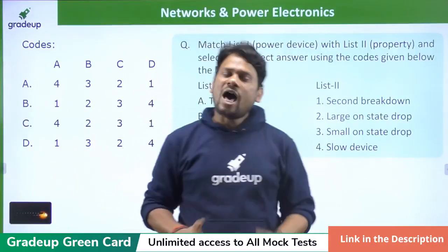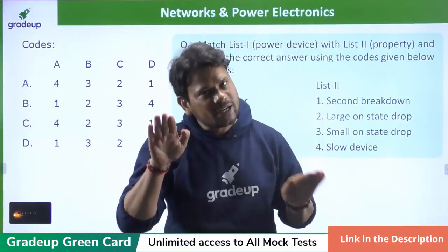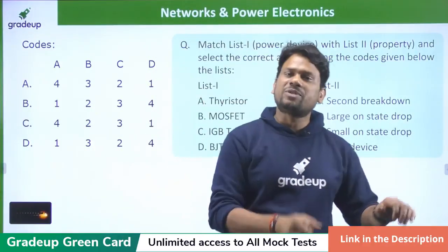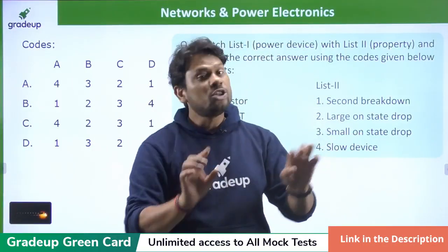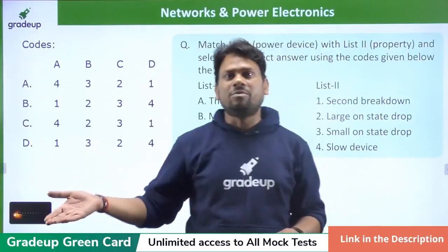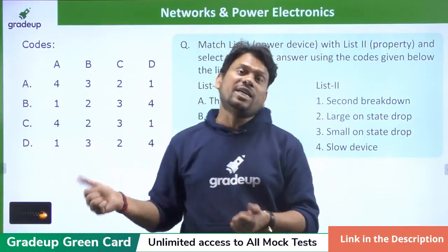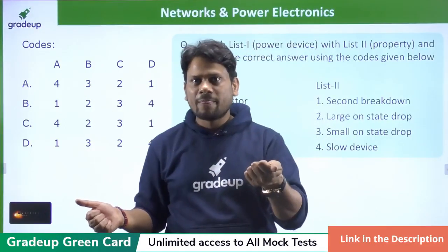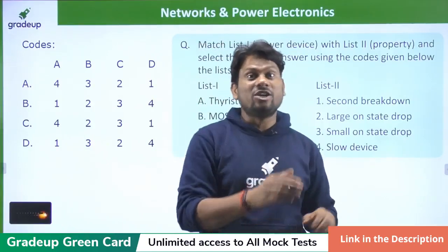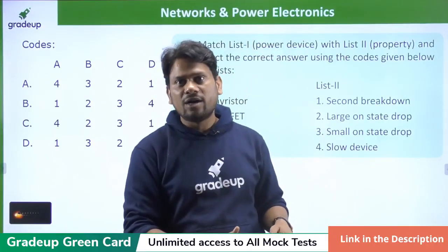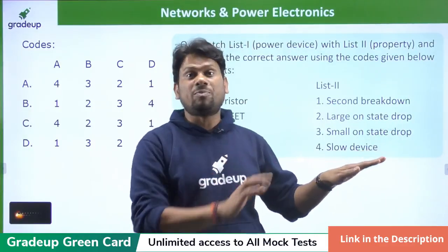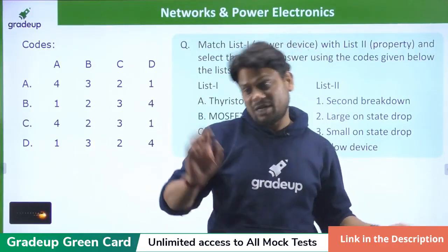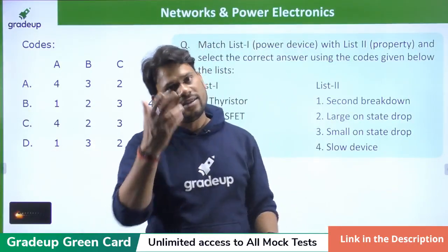आपको सिर्फ क्या ध्यान रखना है, BJT सबसे कम कंडक्शन लॉस देता है, MOSFET सबसे कम स्विचिंग लॉस देता है, इन्हीं दोनों के मॉडिफाई वर्जन से IGBT बनता है. तो IGBT में कंडक्शन लॉस BJT से ज्यादा होगा, और MOSFET से कम होगा. अब स्विचिंग पे आओ, IGBT में स्विचिंग लॉस MOSFET से ज्यादा होगा, बट BJT से कम होगा. दिस इज द थिंग.